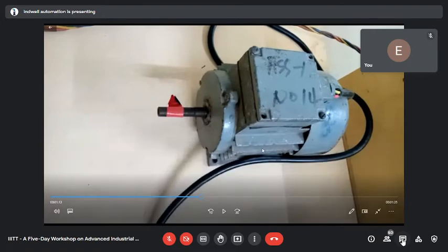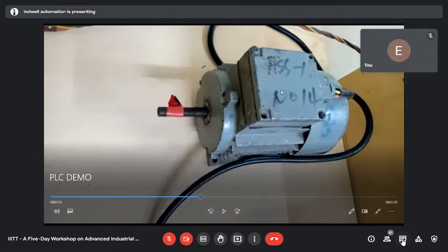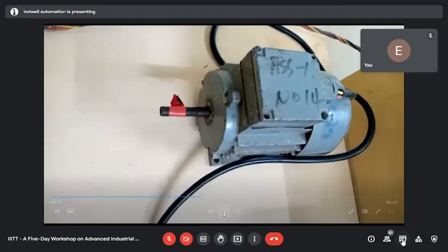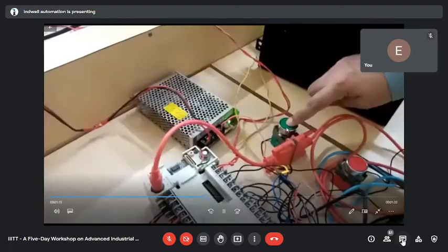To the AC drive we connect only 3-phase motors. Always we connect 3-phase motors to an AC drive. As this AC drive needs 230 volt to get powered on, it returns 230 only, but it splits it into 3 phases. So this motor is a special motor for 3-phase but 230 volt AC. Day after tomorrow we will have more discussion about the AC drive.